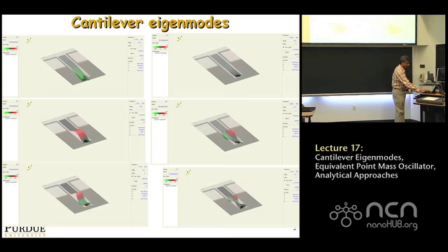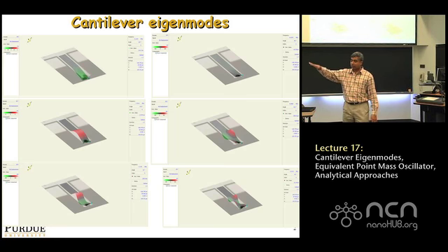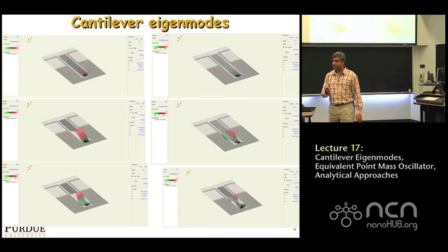It should loop, hopefully. Yeah. So now it's looping. So it's oscillating up and down, and it's got a certain shape. But if you look at the overall shape, it's the same. It's just its magnitude is changing with time, right? It's the same shape basically. So that's what it'll oscillate at when you're at the first natural frequency of the cantilever.